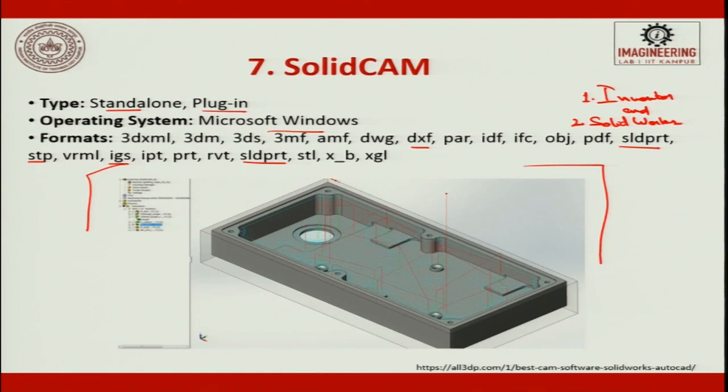So, it takes out the guesswork in milling, turning and other processes by using a patented technology wizard. This software also helps to automatically fine tune your feeds, speeds, depth of cut, width of cut and so on, all the cutting parameters. This CAM software also by itself recognizes the distinct geometrical features of your design and assigns tool paths accordingly. So, this eliminates the need for time consuming manual geometry definition.